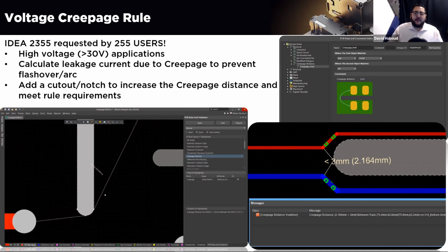You can see here, after you define the rule, this will help you not only in 2D, but it will help you in 3D. You see in this picture here, it is showing you the difference from this layer. It comes through the notch through the board, and the 3D distance to this other trace, right?